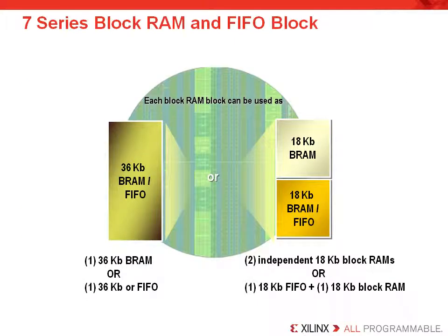The 7 Series block memories allow segmentation of the block RAM into 2 18 kilobit memories. The block memory cannot be segmented further than this. Now this assures efficient usage of the dedicated block RAMs to suit your application, which saves system power consumption and allows you to maximize your memory use. In general, this is a pretty useful functionality since it allows you to not waste the block RAM resources. However, it does encourage the user to make certain they take full advantage of the leftover block RAM.